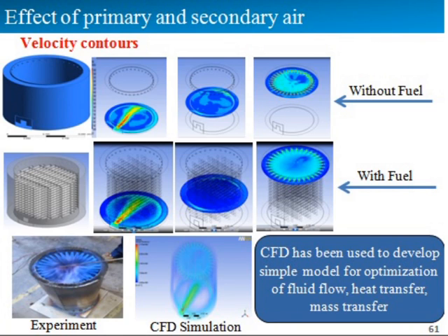I can calculate and estimate how the introduced air is getting distributed within that bed of fuel, whether each bed particle of fuel is getting sufficient quantity of air for its complete combustion or not, and if it is getting sufficient quantity, then the combustion should be complete. So I'll be in a position to estimate without fuel what is the distribution, with fuel what is the distribution.